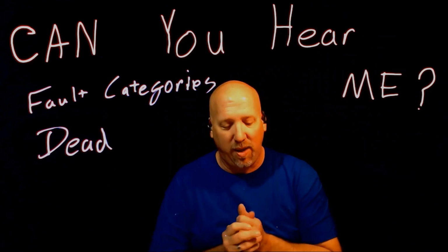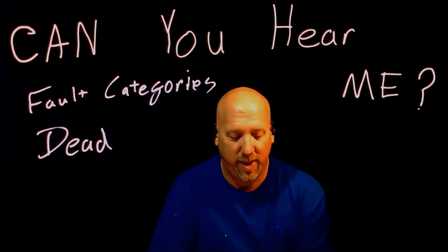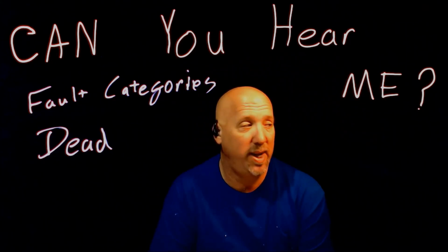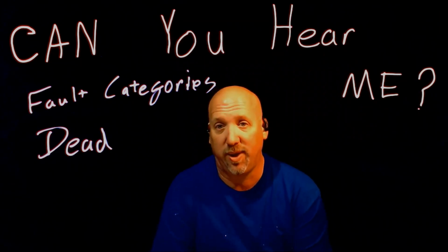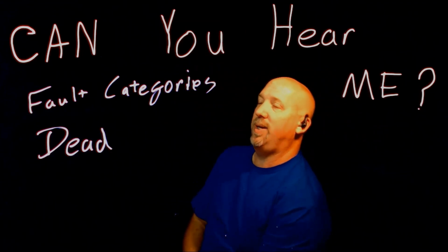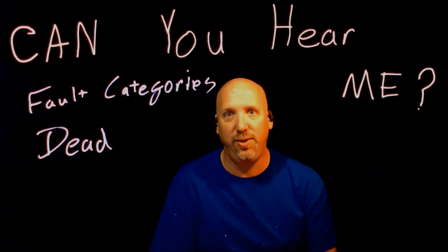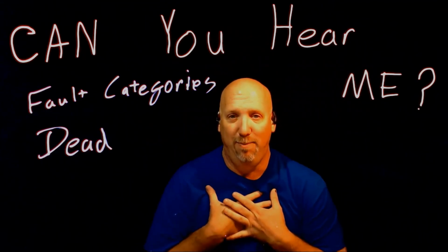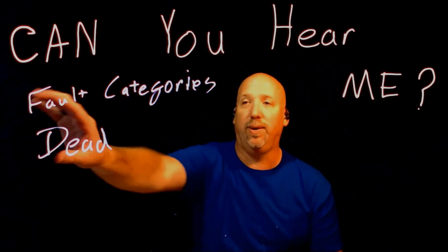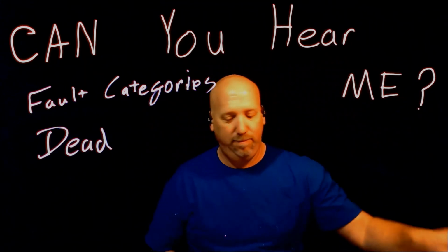You'll usually find all the networks in the vehicle are talking to the gateway, but the gateway is not passing any messages between the networks, and it's not allowing scan tool communications. I've had vehicles that I could not connect with one scan tool, but a different scan tool connected right to it. I'm looking at you, Volkswagen. Sometimes you and Snap-on, you and OTC, Bosch have had issues with me. But that's my history. It may not be yours. So be aware of that. So dead networks, those are some of the diagnostic ways of testing dead networks.